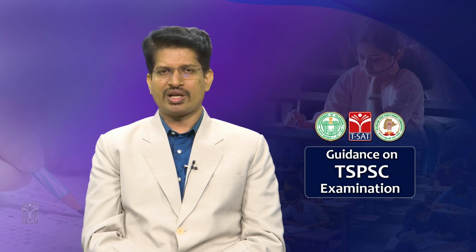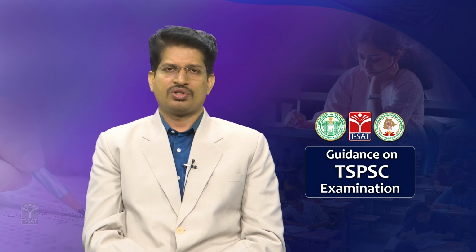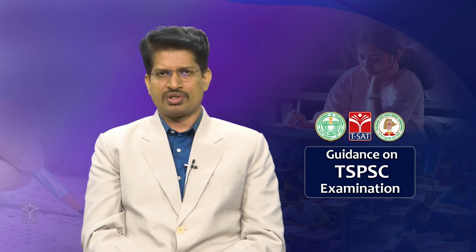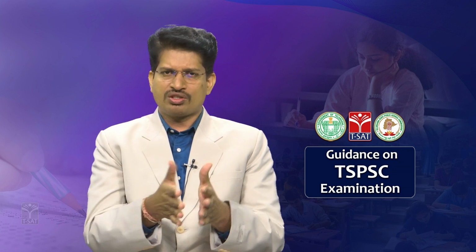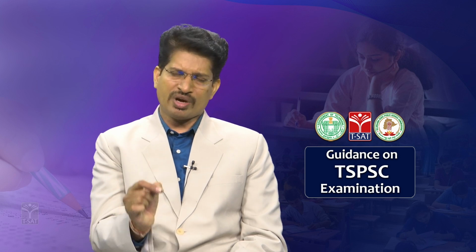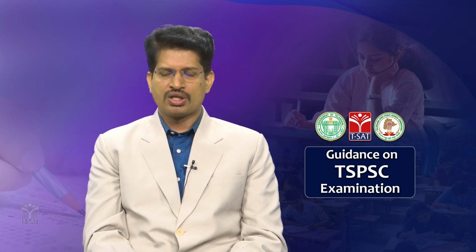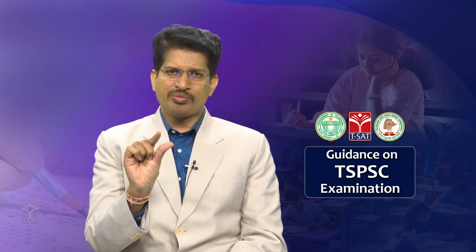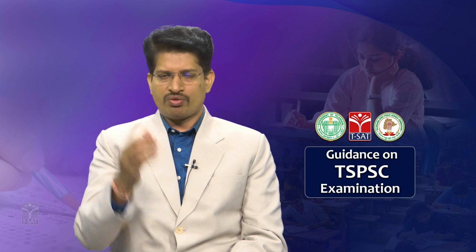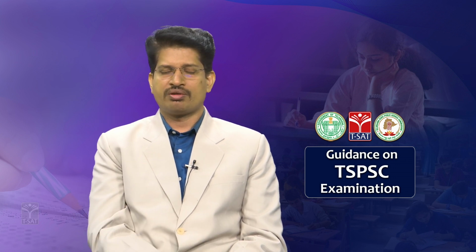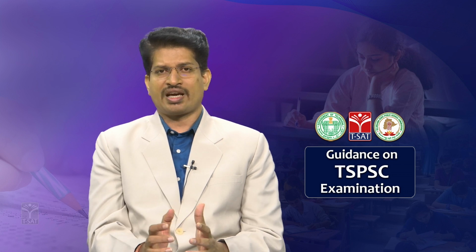So in this process, when in the cold regions, especially when water enters into the fracture zones and the temperature is gradually decreasing, the density of water is maximum at 4 degrees. Because of this, the volume occupied by water will be minimum at 4 degrees, and water seeps into the cracks. From 4 to 0, when the temperature is decreasing, the water starts expanding.